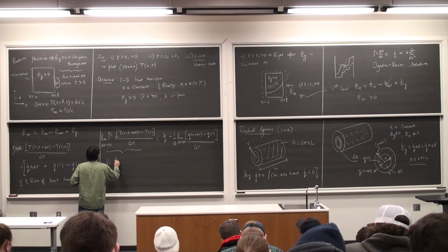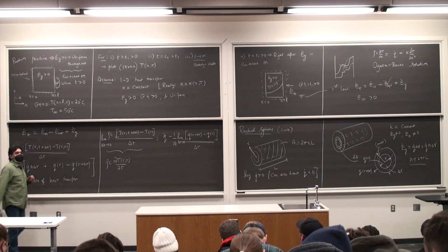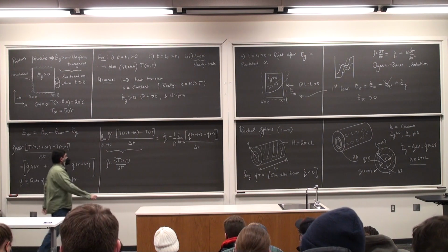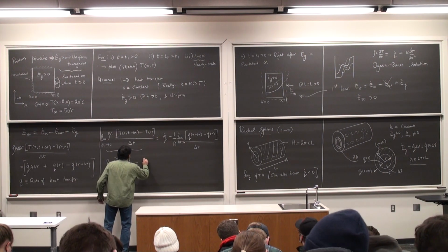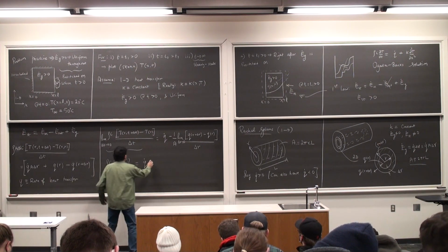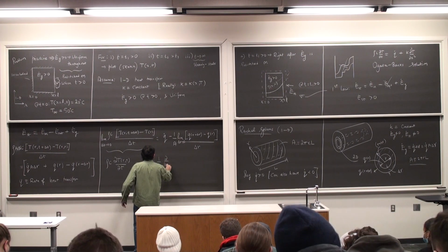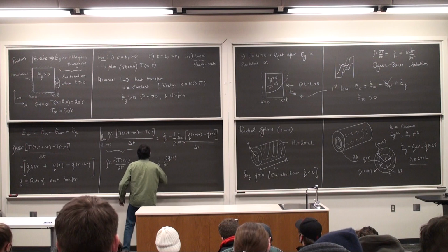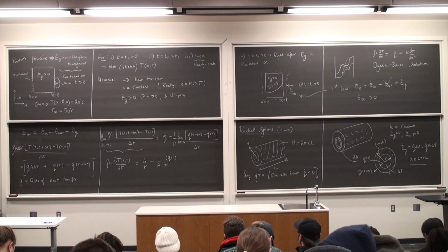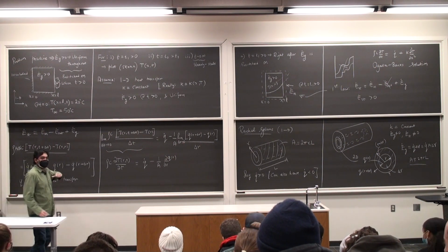Okay, so here I have rho times C dT by dt. T is a function of R and t. This is equal to Q dot, which does not undergo anything, minus 1 by A times d by dr of Q. Now Q of R is once again the rate of heat transfer, which according to Fourier's law is the flux times the area.